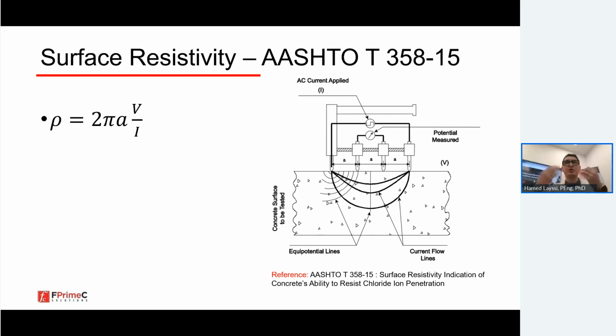So if we have a more durable concrete that doesn't allow chloride or carbon dioxide to penetrate easily, we are basically creating an environment that is less prone to corrosion. If we are, for example, using glass fiber reinforcement instead of black steel, or if we are using stainless steel rebar, we are eliminating one of the reasons for aggressive corrosion. So these are things that we can control. Now, because this presentation is about concrete, I'm going to focus on how we can test concrete for better durability.